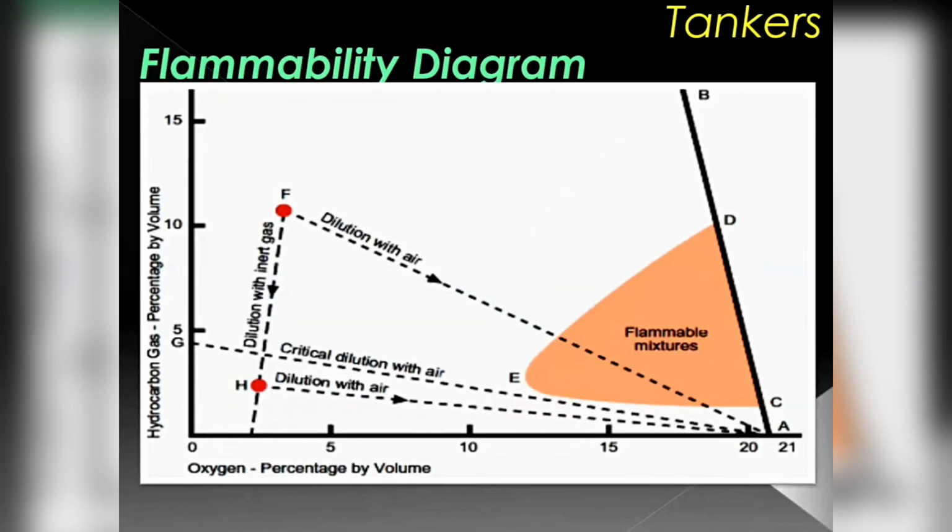You must have heard of people doing tank cleaning and a ship has exploded, and they have done the tank cleaning in a gas-free state. You prepare the tank, you do the crude oil washing, you do the tank cleaning, you open and you find a lot of sludge inside. That means crude oil washing and tank cleaning was not done properly. You gas free the tank and then you open and see that there is a lot of sludge there. Some smart chief officer just closes the hatches, closes the tank again, and does the second tank cleaning. Carry out the tank cleaning again without inerting the tank.